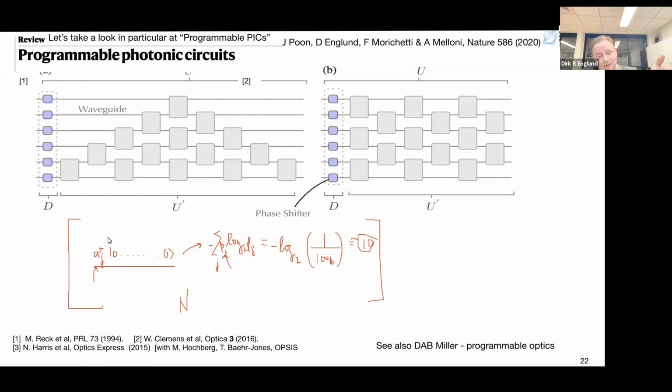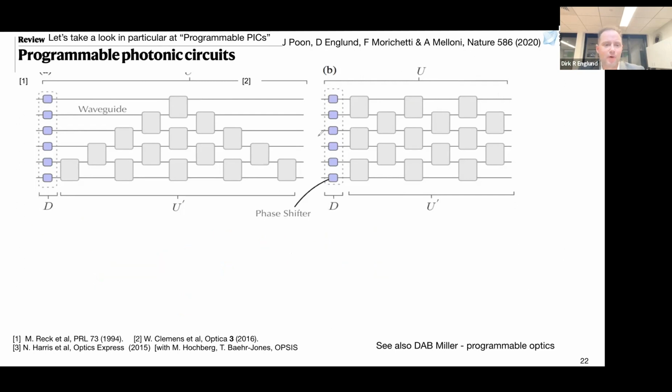And that was the reason why we wanted photonic integrated circuits. It's not that we have to do everything in photonic integrated circuits. You have to have a pretty good reason to go that way; otherwise, you should use free space modes. But we wanted a large number of waveguides. So we did several fab runs with foundries and our own efforts, fabricating these photonic integrated circuits back in 2011 or 2012 to make these modal transformations on high dimensional basis states. And the thing never worked. We could not get it to work.